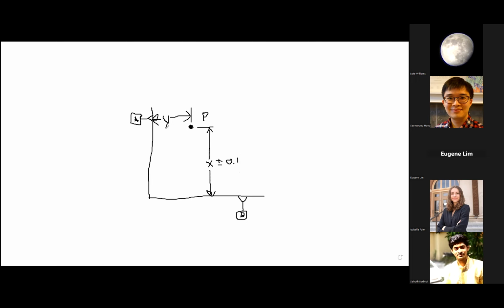And this applies to both X and Y. Okay. So now this fully constrains our point P here. It gives point P limits as to where its location can be using just tolerancing without a control feature like we saw previously.